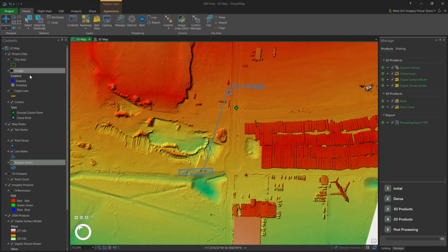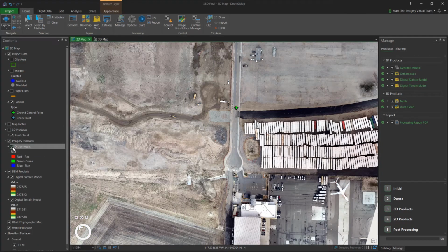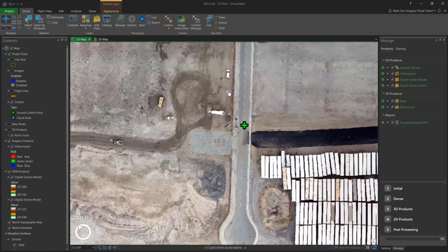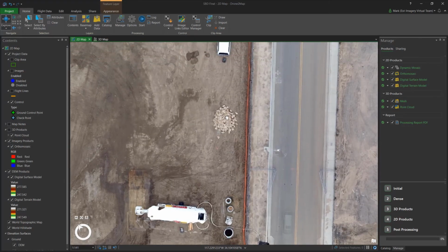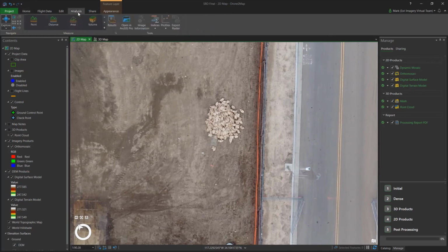I've created a plan for my sandbags, but it would be great to get an idea of how many I have available for this project. Since I've created a digital elevation model, I can use my 3D analysis tools with a little knowledge of my construction materials to solve this problem. On this construction site, we use standardized sandbags, but they come in different capacities based on their dimensions. If I could measure one, I could look up its capacity.